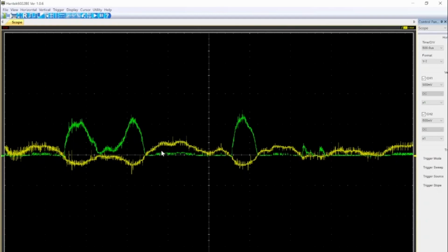So that's my first improvement. I need to find a way to take our incoming power voltages, take our power, and somehow create a negative voltage from that, so that we can use this amplifier to amplify both sides of the wave, so we get nicer sound coming out of it.